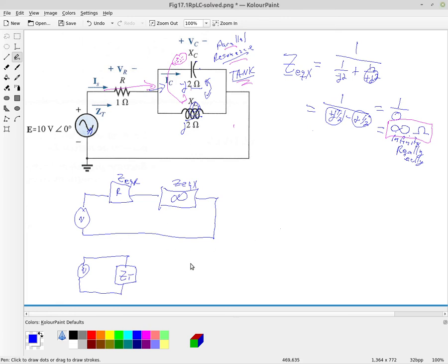So if we were to try to calculate, by the way, these had J's in them, right? But you had half a J minus half a J. The J's disappeared, so you're just left with nothing. Okay, so there's no J, there's no phase angle in here. And so our total impedance then is going to be our resistance of 1 ohm plus our infinite resistance of the tank circuit. All right, and if you add 1 to infinity, you get a slightly larger infinity.